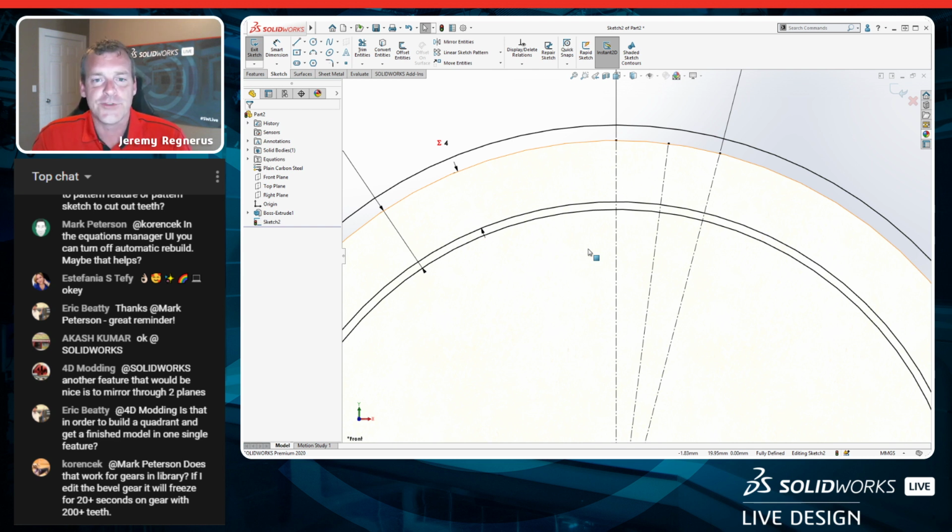I'm going to do this with an arc. I'm not going to do this with an involute spline. That would get into a whole new level of complication. And if you really need to draw and create an involute spline, you're probably the person creating the gear, and this probably isn't new to you. This is really for, I need a gear model in my design that I customize, and I'm going to send the specs for that gear to somebody. So keep that in mind. I am creating this with an arc, not an involute spline. I just want to get that out of the way right away.